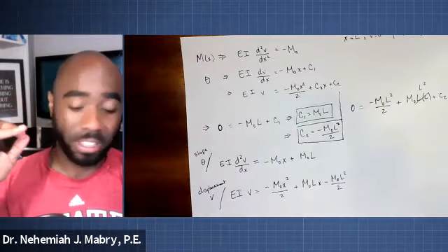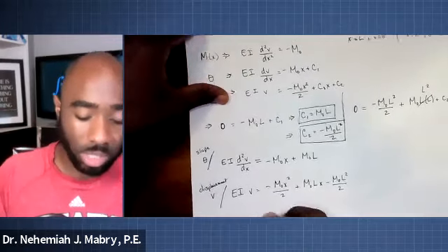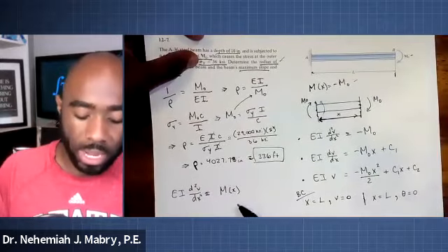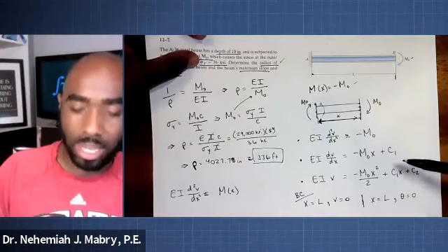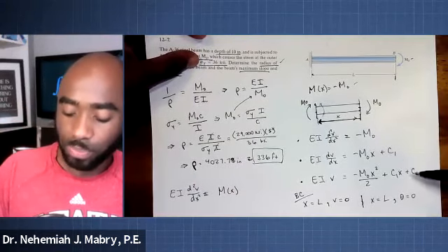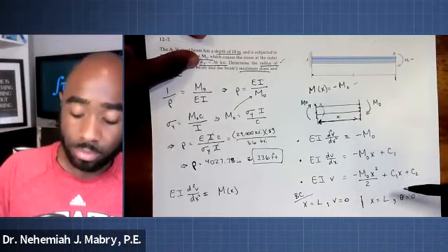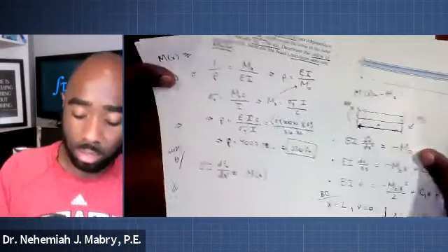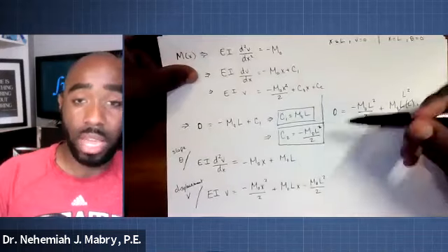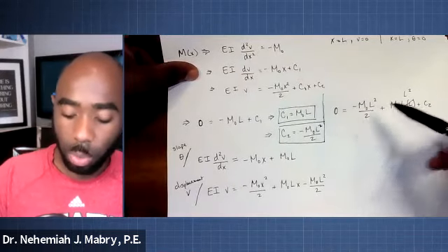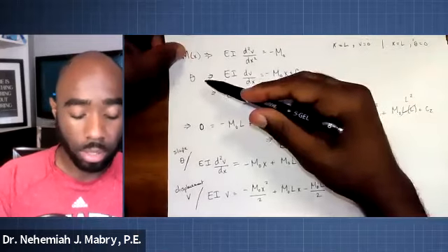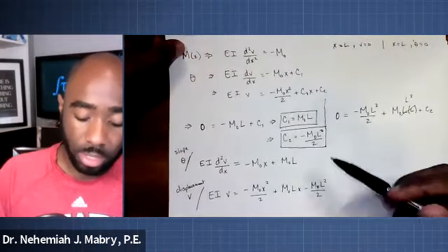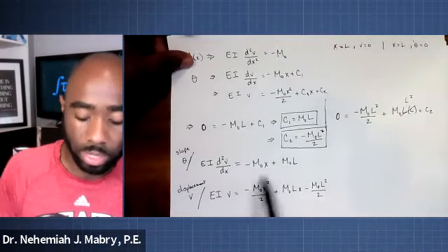Make sure you soak that in. We got our equations originally. Just to review really quick. By finding out what m sub x is, we took the derivatives of, or the antiderivatives of it, rather, to get these equations. We use these boundary conditions to then solve for what those constants are. And when we solve for those constants, we basically rewrote the equations we cared about, the slope and deflection, including these constants, and this is what they look like.